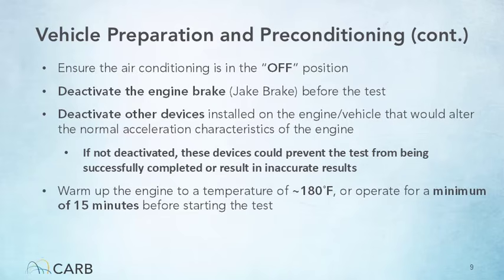Also, deactivate other devices installed on the engine or vehicle, such as the heater or auxiliary devices that would alter the normal acceleration characteristics of the engine. If these devices are not deactivated, they could prevent the test from being successfully completed or could result in inaccurate results. Prior to performing the smoke opacity test, it is also important to warm up the engine to a temperature of approximately 180 degrees Fahrenheit before starting. This can be achieved by operating the engine for a minimum of 15 minutes prior to performing the test.